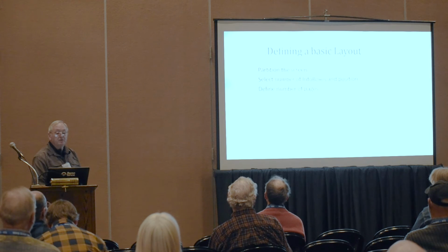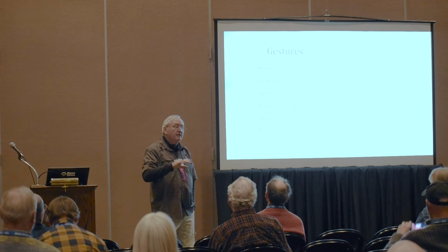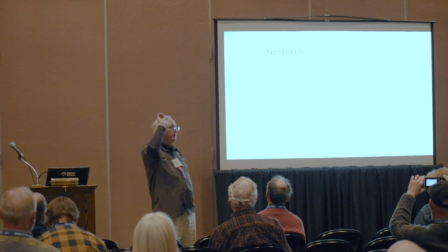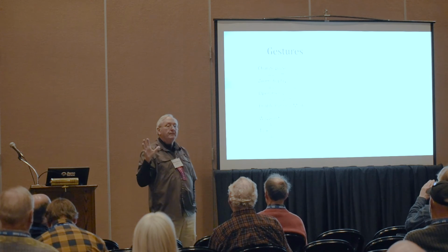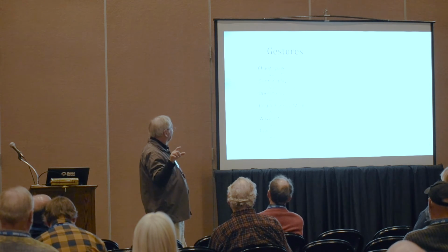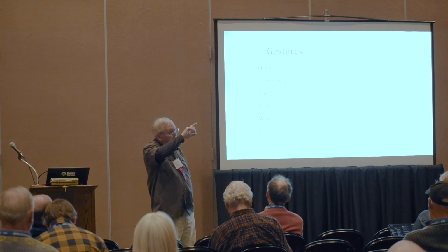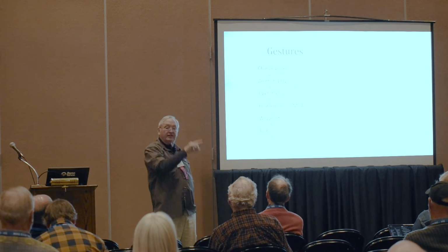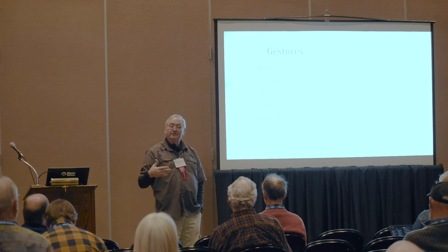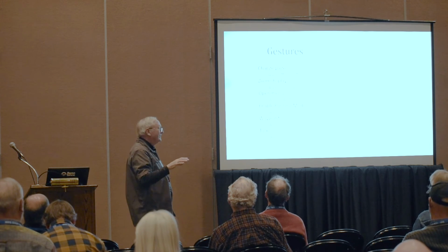We're going to do all these things, but I want to talk about gestures, because you're going to see me doing gestures. Touchscreen, remember touchscreen? So you go down and up in one motion without picking your finger up, and you will go to the menu system. If you go down and to the left, you're going to open up the waypoint page. If you go down, right and then down, like the letter T or the letter L, the letter T is going to give you the task definition page. Now that's a little bit further down the way. You're probably not going to try this for a task quite yet.